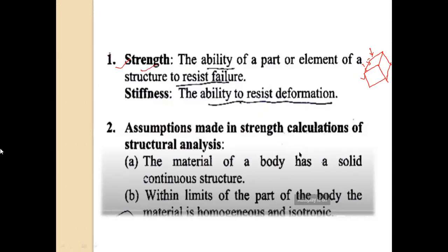After that, the next point is stiffness. Stiffness means the ability to resist deformation. Please remember the basic difference between strength and stiffness. In strength, we find the load carrying capacity, and in stiffness we find the deformation. This is the basic difference you have to remember.